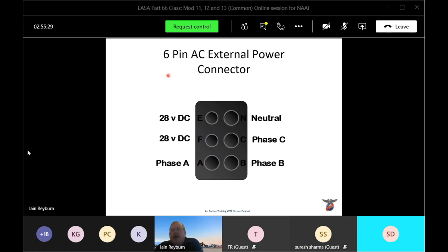Have a read through the notes, especially the reactive and active power sharing, but just listen to what are a lot of complex words in there. In reactive load sharing, it is a mutual reactor which goes to my voltage regulator. Active power is a load controller, and that regulates the constant speed drive unit by the magnetic trim. If a generator fails, either the load controller or the mutual reactor is shorted out by the auxiliary contacts. And in an aircraft, each generator should take equal amounts of active power and equal amounts of reactive power.